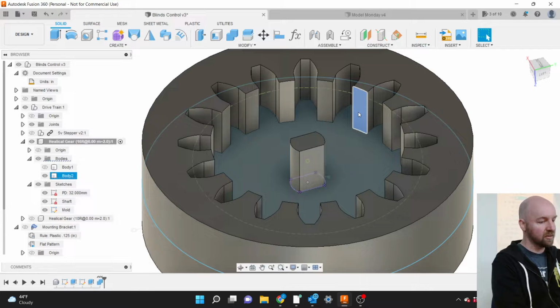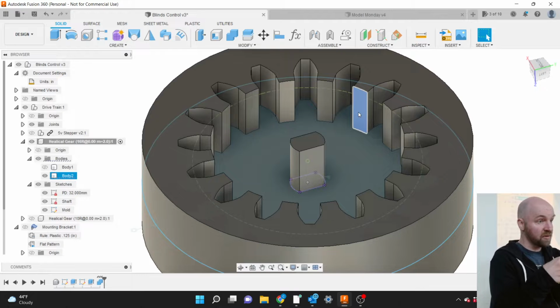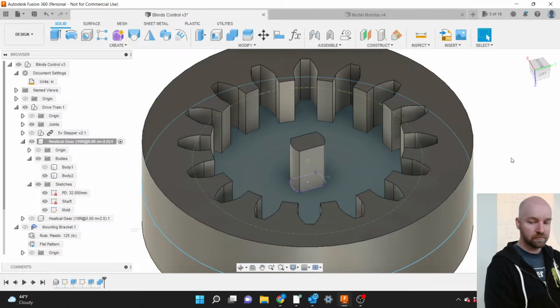So this plane kind of needs to be angled inward. But depending on how thick your mold is and what your material is, if it was a soft material or a material that shrinks significantly when it cools, it might separate away from those walls on the outside and be able to pull up nicely. But it's a kind of case by case. But in general, you want to have a draft angle on your molds.